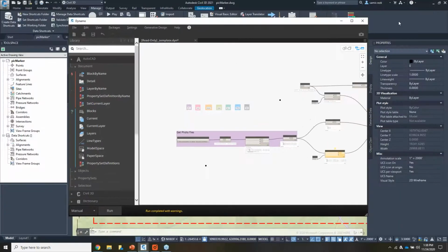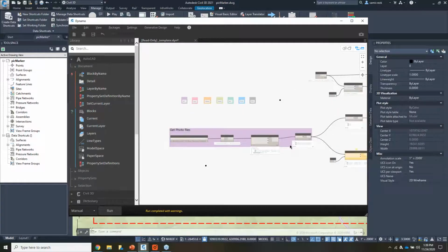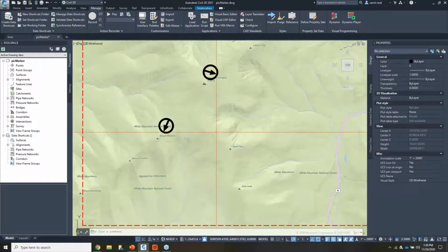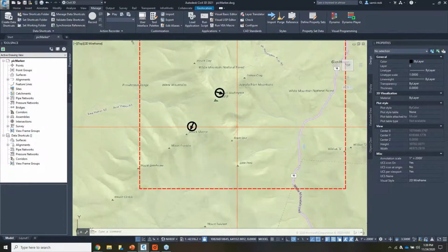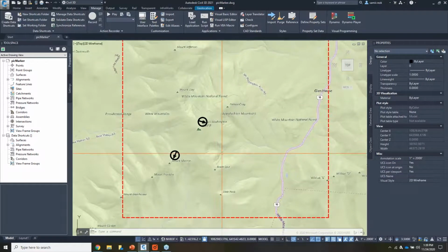But that was a quick overview of the Dynamo interface, capturing information from the library, organizing them, lacing them up one by one, and grouping them for documentation purposes. Once the graph is created, you don't necessarily need to run it in Dynamo. You can always run it in Dynamo Player. It makes it easy and attainable to a lot of people, and more flexible too for sharing.